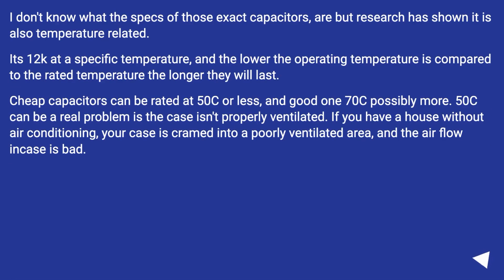I don't know what the specs of those exact capacitors are, but research has shown it is also temperature related. It's 12K at a specific temperature, and the lower the operating temperature is compared to the rated temperature, the longer they will last. Cheap capacitors can be rated at 50C or less, and good ones 170C possibly more. 50C can be a real problem if the case isn't properly ventilated, if you have a house without air conditioning, your case is crammed into a poorly ventilated area, and the airflow in the case is bad.